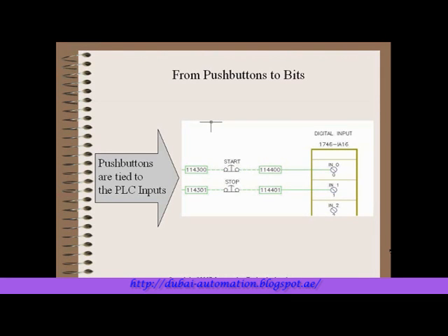So what's the difference between the PLC and the regular hardwired option? Well, with hardwired, you saw we take our push buttons directly to a relay, and it acts directly upon that relay. With the PLC, our start button comes into an input card. It's wired directly into cards that interface with the processor through a rack or some other means.